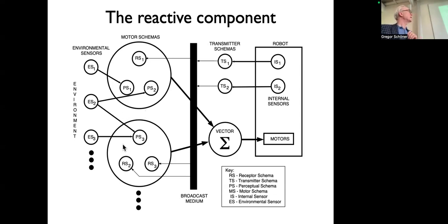And then on the output side, they are just specifying something for the motor systems. The motor system ultimately is a vector, depending, for instance, if it's a vehicle, it might be a vector that is just a velocity vector, or could have some additional degrees of freedom. And every module might only fill some of the entries into that. Like you could have a speed control that only is the length of the velocity vector, and another one could be orientational control and so on. So they don't all have to specify everything, and they would just be added up.